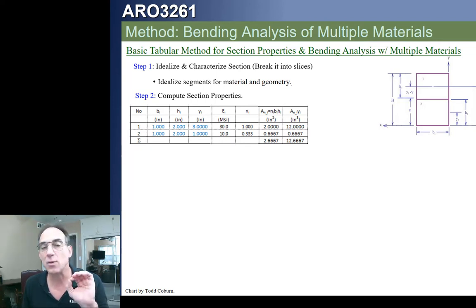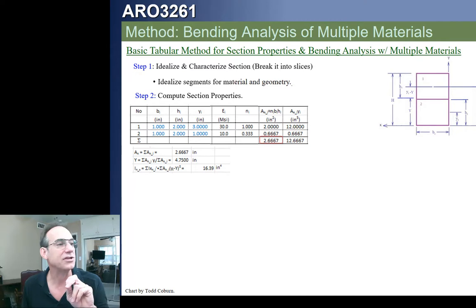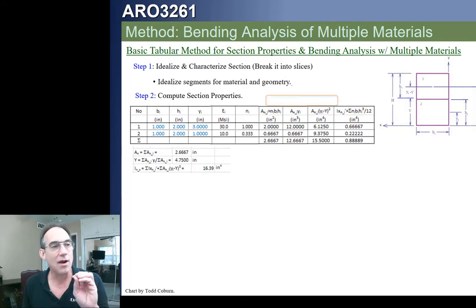We're going to sum each, and we're going to use those, as we did before, the summation of the inertia times y bars divided by the summation of the inertias to calculate our y bar of the section. Also, you'll notice that the inertia of the section is just summing that first column there. Or actually, it's the 1, 2, 3, 4, 5, 6, 7th column, okay? We then can go on, now that we've calculated our y bar, to calculate the inertia times the y minus y bar squareds and the 1/12 BH cubes.